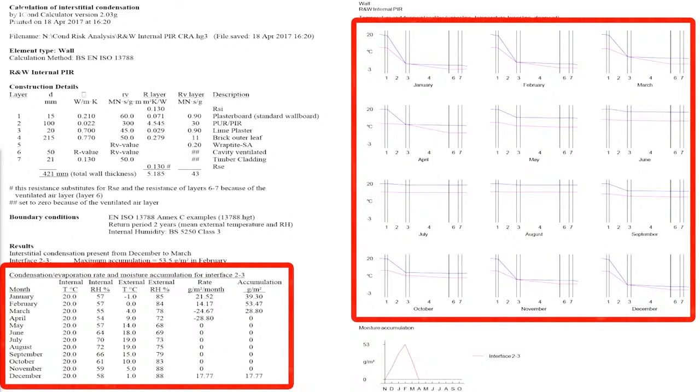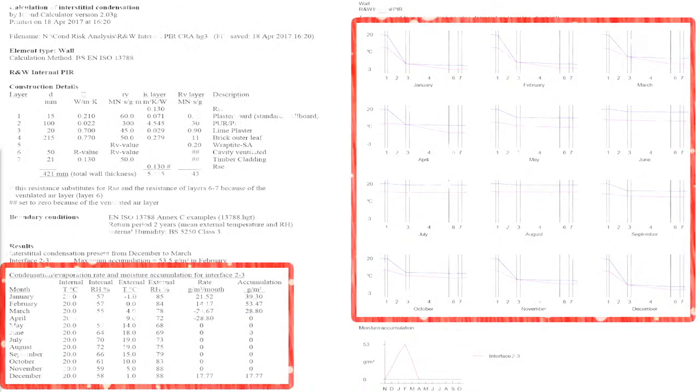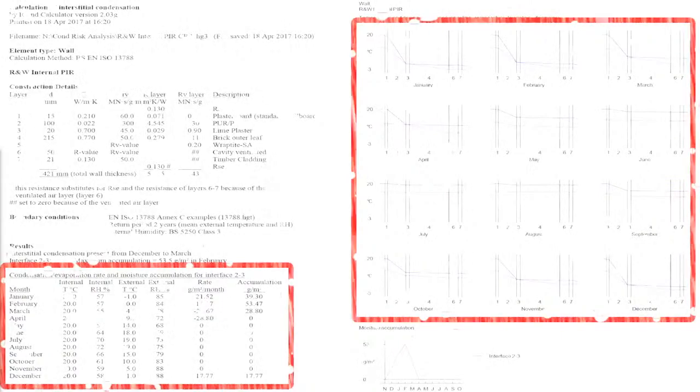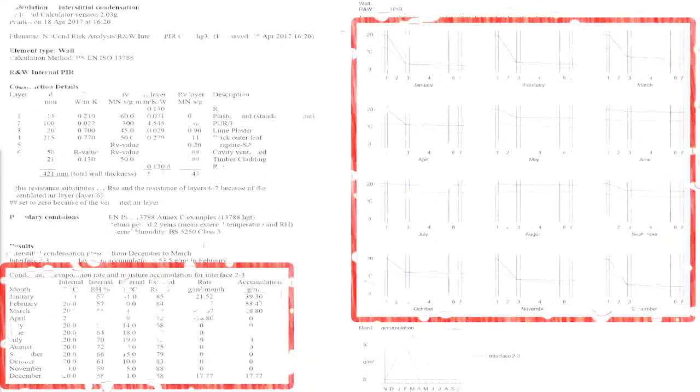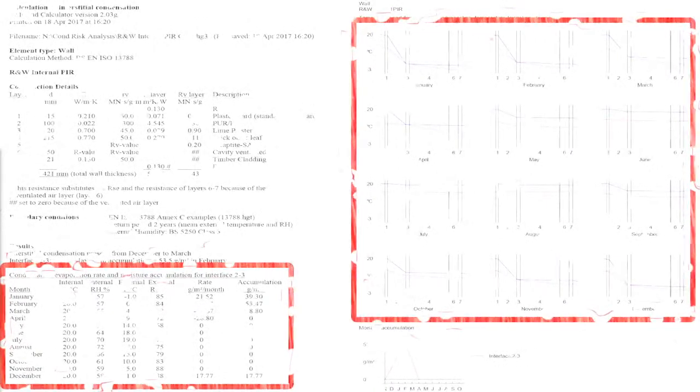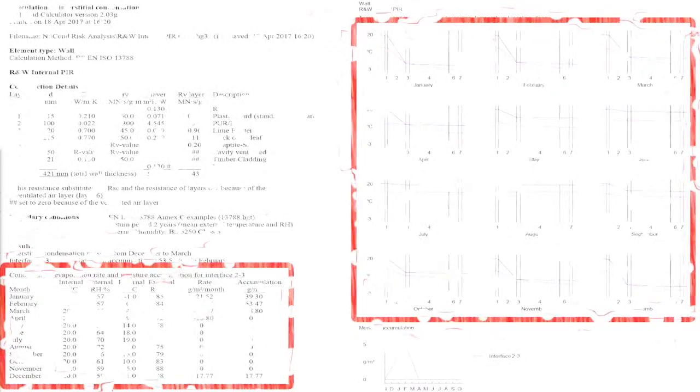It also completely omits the key feature of driving rain from its calculations, does not measure absorption or porosity, and therefore fails to identify potential risk attributed to the aspect of moisture storage. While this basic model is acceptable in some cases and useful for providing a rough guide to avoiding the worst and most obvious problems, a proper assessment of the wetting and drying balance of structures requires a more substantial approach.